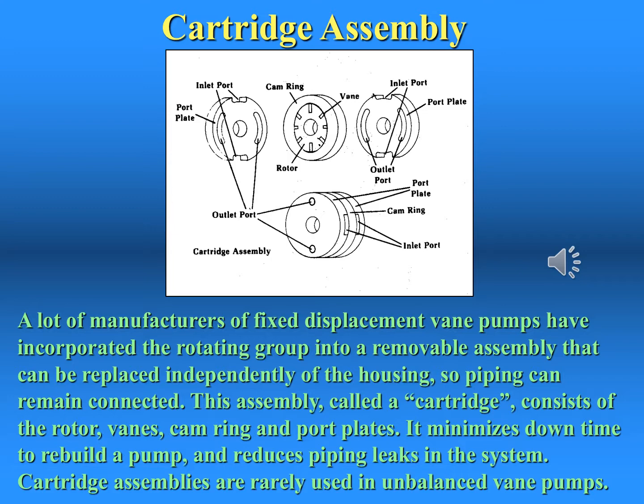Many manufacturers of these types of pumps make available a service kit called a cartridge assembly, which essentially replaces all of the worn parts of a vane pump, and they are quick to install.